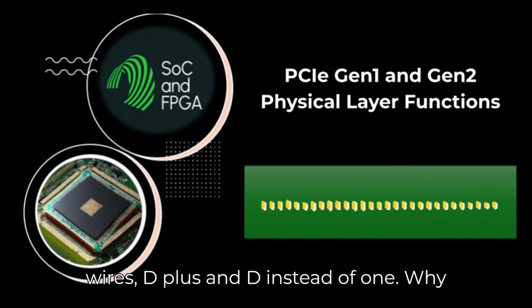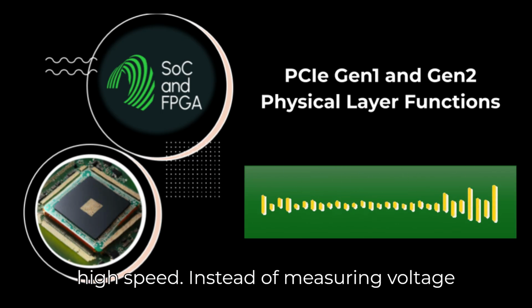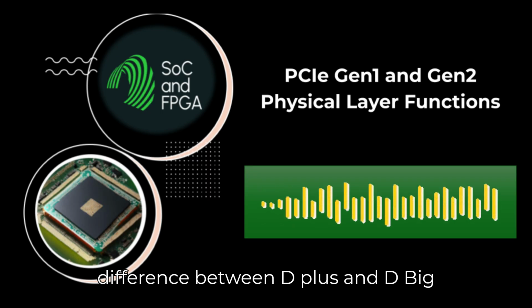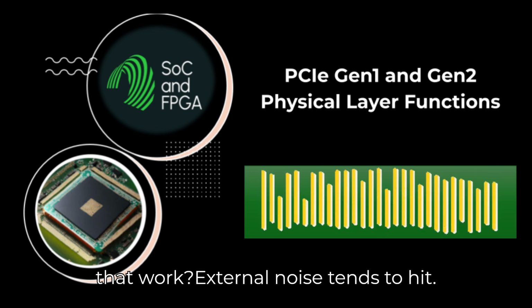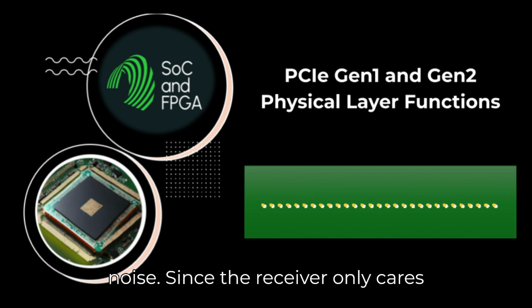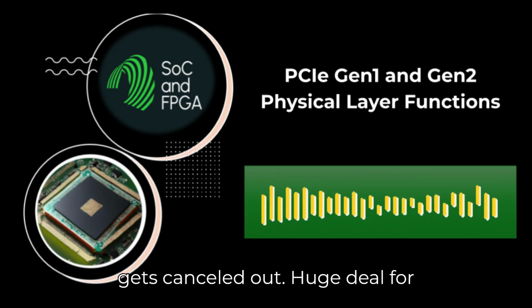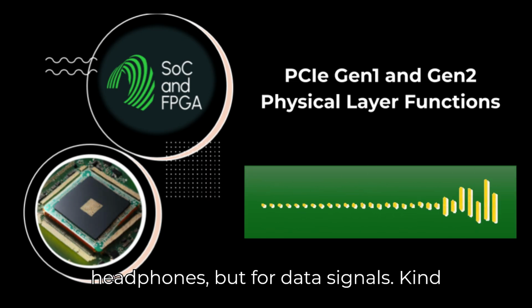Using 2 wires, D+ and D-, instead of 1. Why is that so critical? It's fundamental for high speed. Instead of measuring voltage against ground, the receiver looks at the difference between D+ and D-. Big advantage number 1, noise immunity. How does that work? External noise tends to hit both wires similarly. That's common mode noise. Since the receiver only cares about the difference, that common noise gets canceled out. Huge deal for reliability. Like noise-canceling headphones, but for data signals.